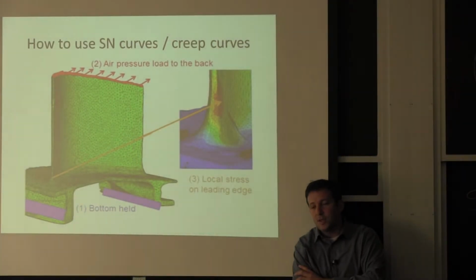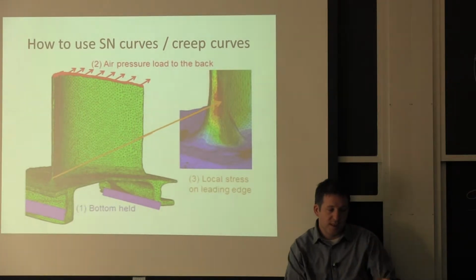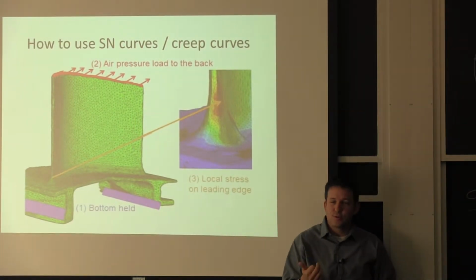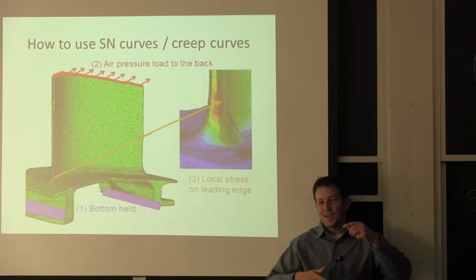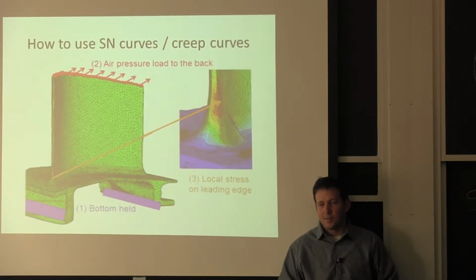And one of the biggest issues with making this type of analysis is you don't know exactly your stress level, because it all has to do with the dynamics in the engine. You can instrument some of it, but I wouldn't put a strain gauge there and try to run it. So there are some limitations as to how precisely you know your stress.